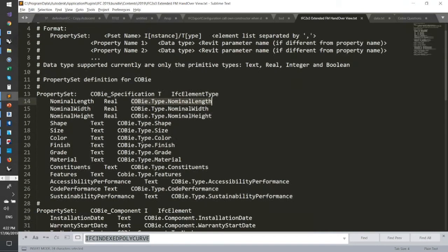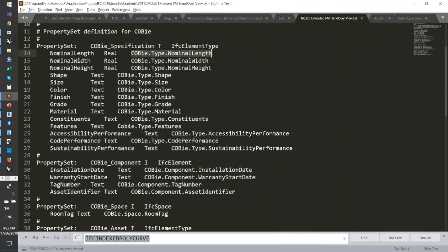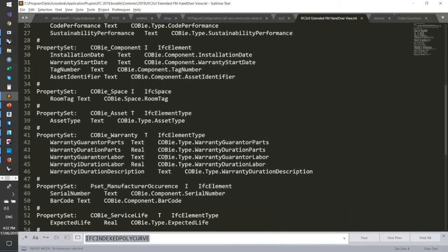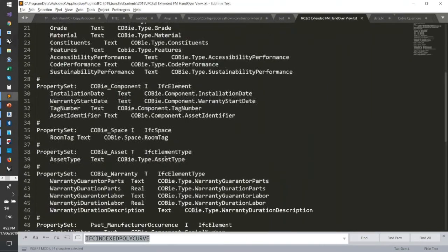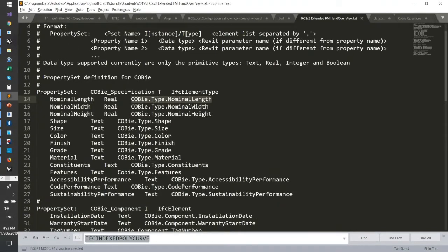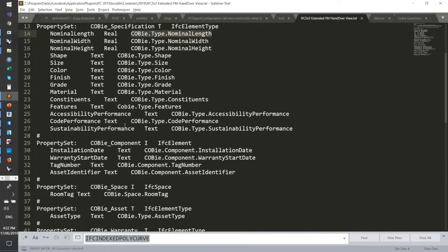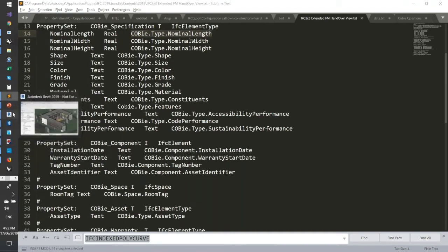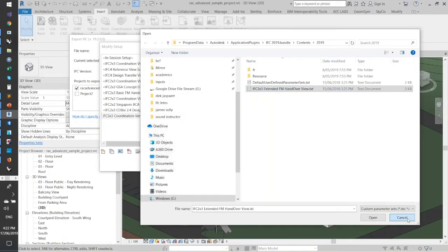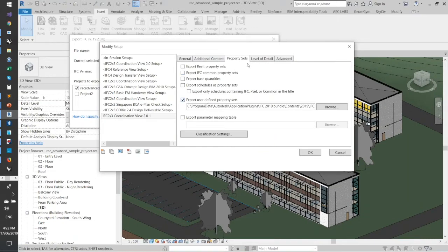And you can actually map multiple parameters into one property. What we also don't want to do is load other properties into Revit and have a duplicate fire rating or something like that. You can control and configure that export so that the mapping from a built-in parameter appears in an IFC property as part of this process.